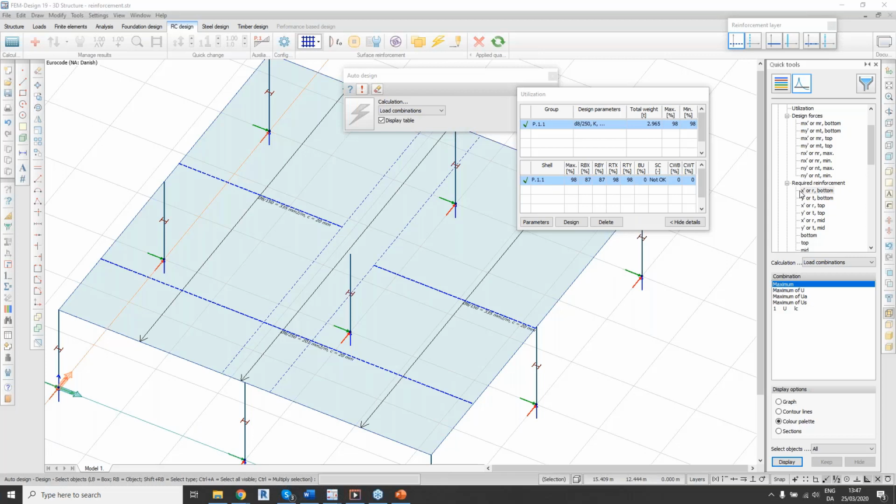Regarding this, I know that we do get a lot of questions about how FEM design actually applies reinforcement, and a lot of people say that it puts too much reinforcement everywhere. We should also remember that even when we have small stresses, the program will automatically try to put reinforcement according to the minimum reinforcement. So it might be good to turn off the minimum reinforcement and then turn on the reinforcement, and you can play a lot with the reinforcement to get a very good answer.